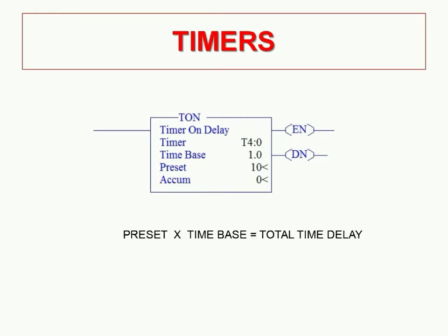Next is, yes, this is the important thing. Total time delay doesn't mean that it is the preset value. Okay, preset value is not the total time delay. Total time delay depends upon the preset and time base both. So preset into time base is total time delay.